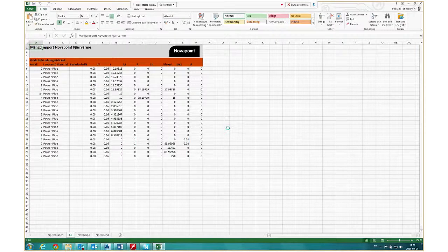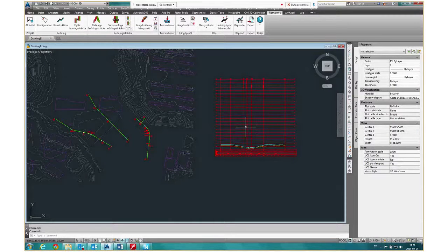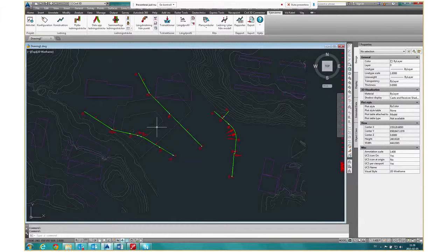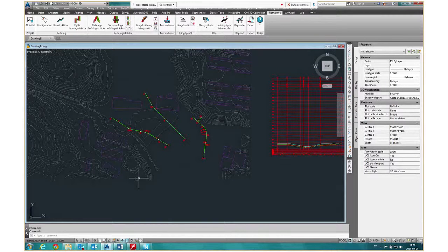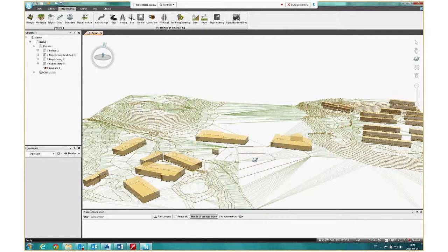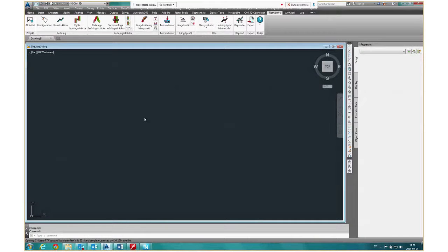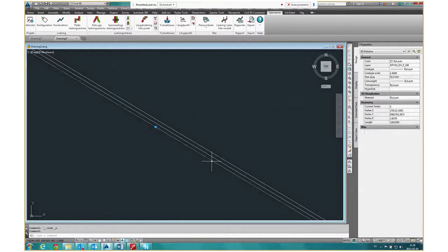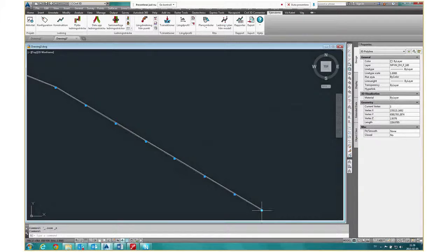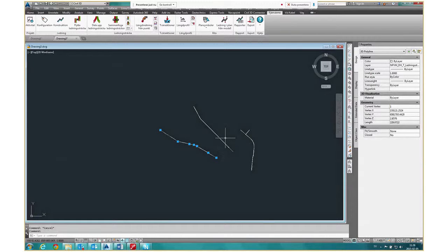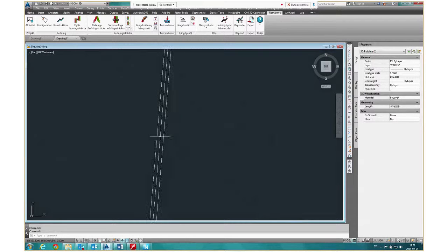If you want to see this in NovapointDCM, because maybe in here we have imported a lot of existing pipes, and we want to see it, it's no problem. We can just open a new empty drawing, and we can draw these lines in 3D. So now we have 3D polylines instead. Every point here has a zeta value, so it's right in the height here in the coordinate system.